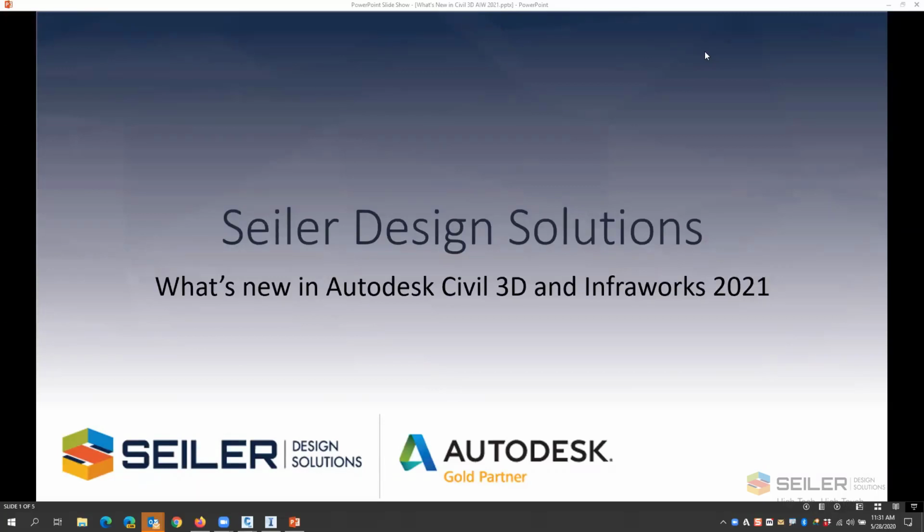Those of you who are using Civil 3D 2018 or plus products, 2021 is completely compatible with previous versions. It does use the AutoCAD 2018 drawing format with Civil 3D 2020 compatible objects. 2018, 19, 20 and 21 are cross-compatible with each other to a point, and I'll highlight where those points are as we go through.